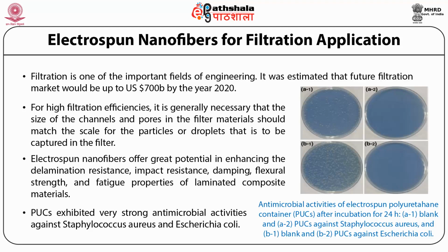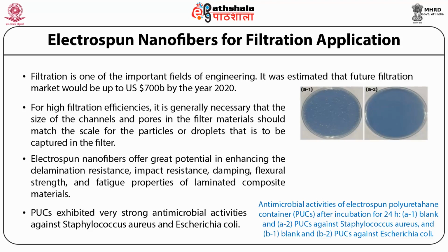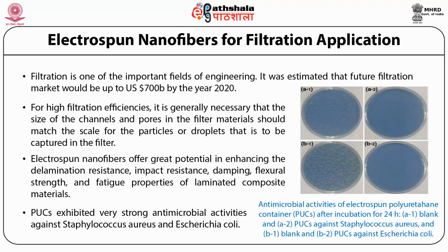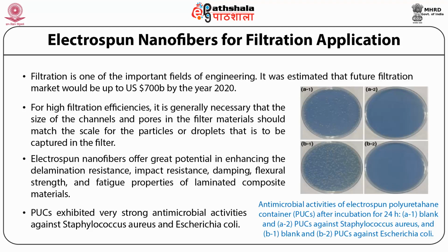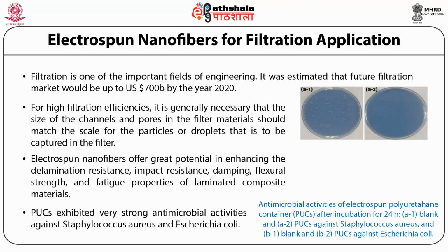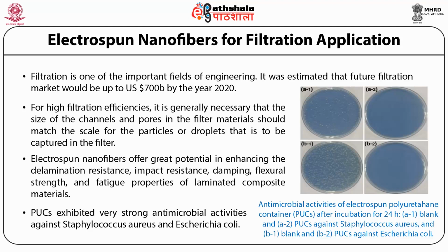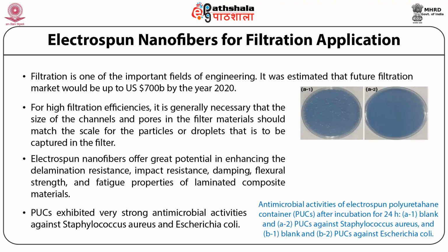electrospun nanofiber non-wovens have been widely used in air and liquid filter applications. Usually, the particle filtration occurs via multiple collection mechanisms such as sieving, direct interception, interstitial impaction, diffusion, and electrostatic collection. Till now, many highly efficient nanofilters made from nanofibers have been realized.